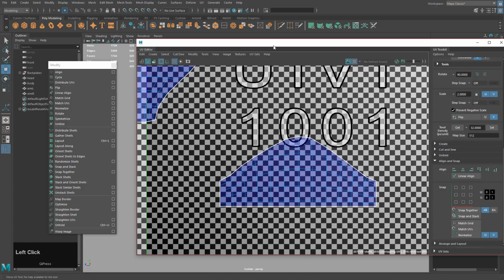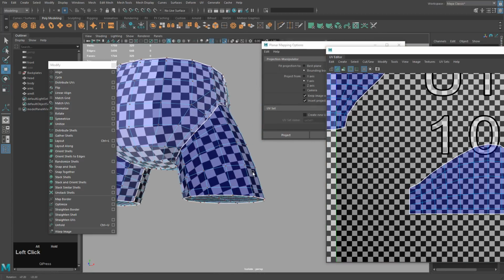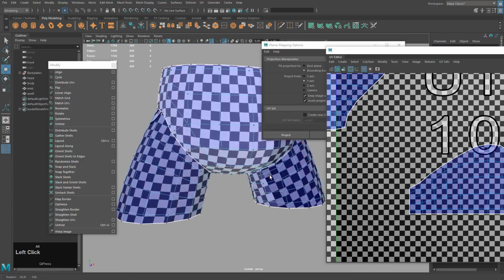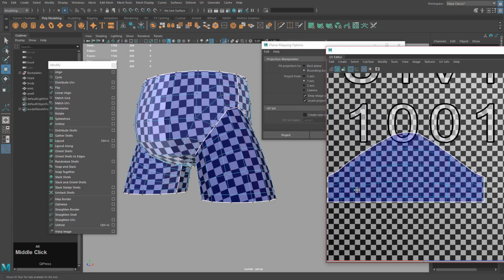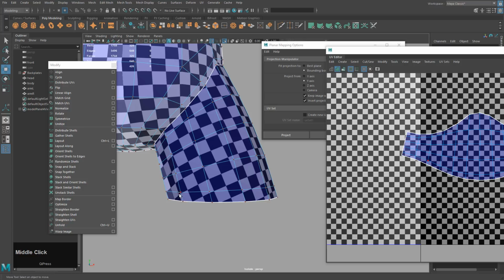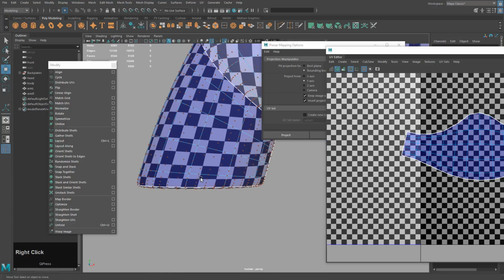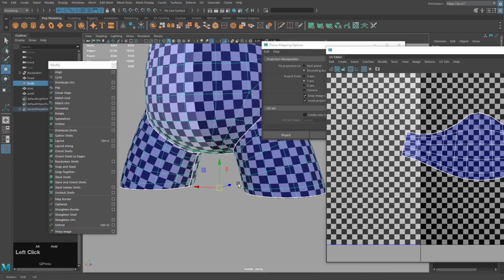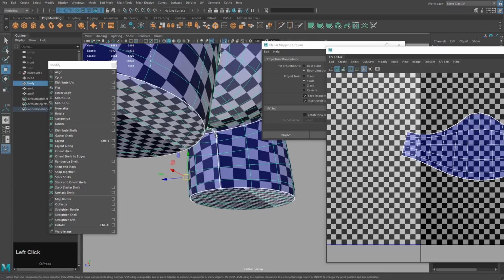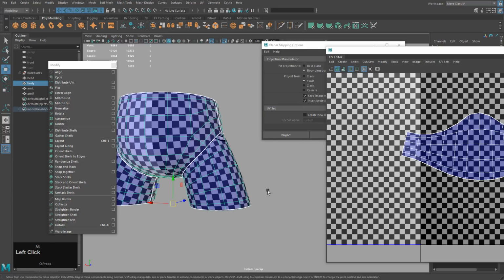There, we can preview this by pressing this button. This will show us a checkerboard on the foot there. And if we look at this foot we didn't fix the bottom yet, and you can see what's happening is the grid is wrapping, it's going right through the bottom of the foot. So when you paint this, it's going to be harder to paint on this. But on this one, you can see it's aligned right to this edge, and it's staying nice and flat. And the seam is nice and clean. So we just need to match that on the other foot.